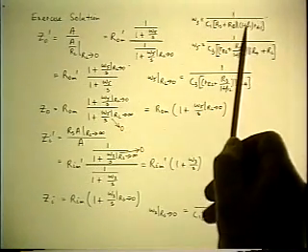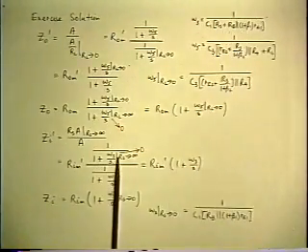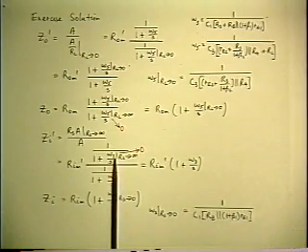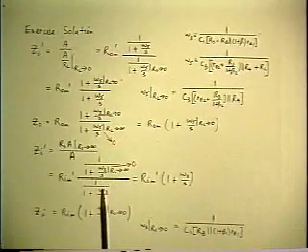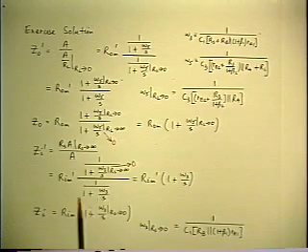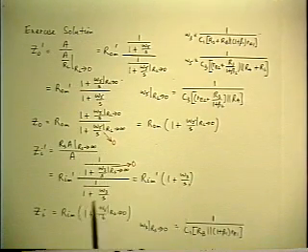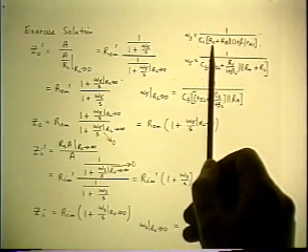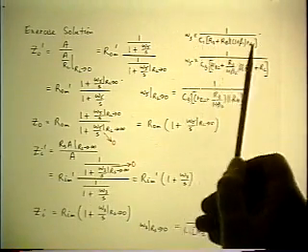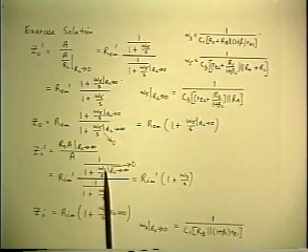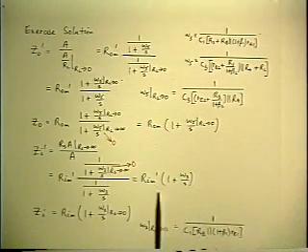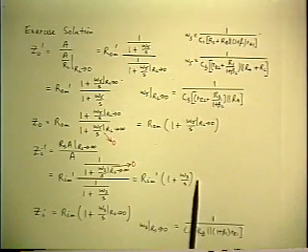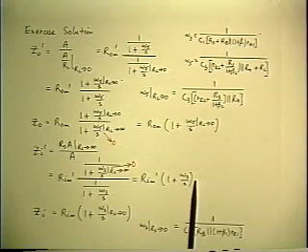You look at the other corner frequency, it does have RS in it, so you're going to have to keep it. And the bottom one comes around on top, unchanged. And when you look at omega-3, as RS goes to infinity, it goes to 0. So the entire corner goes away, and you're left with a mid-band value together with an inverted zero.